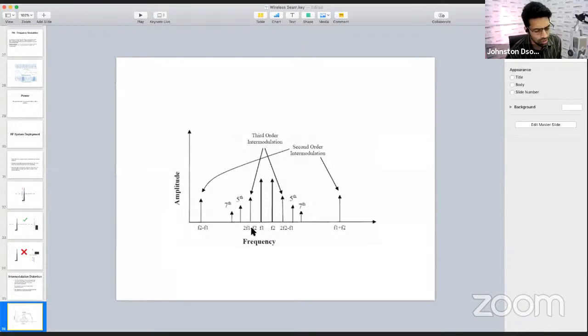Will RF work in studio recordings? Yeah, they will, but I don't suggest that you use RF in the studio. See, what is happening is, every time the RF is getting modulated, the audio is actually compressed. And depending upon the system that you're using, what is the quality of the modulation and demodulation, you might start hearing it. That's the reason if you buy very cheap wireless mics, they sound really bad. They're very noisy, they're very harsh, because the modulation and demodulation is not very good quality.